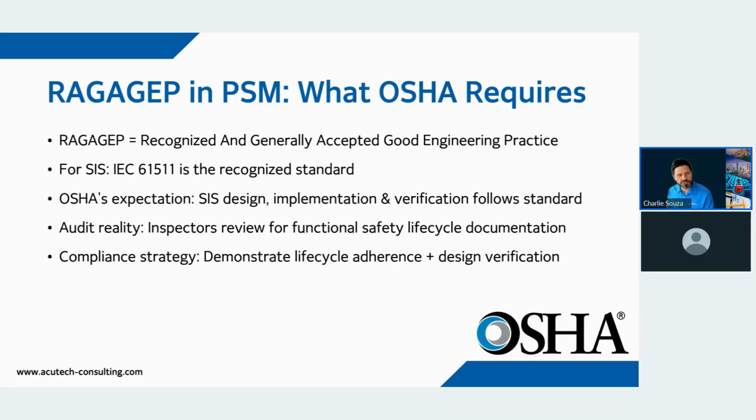RAGAGEP, for those of you who are not familiar, stands for Recognized and Generally Accepted Good Engineering Practice. Again, 61511 is the one we're talking about. And OSHA's expectation is that your safety instrumented system is designed, implemented, verified, and validated following the requirements of 61511.